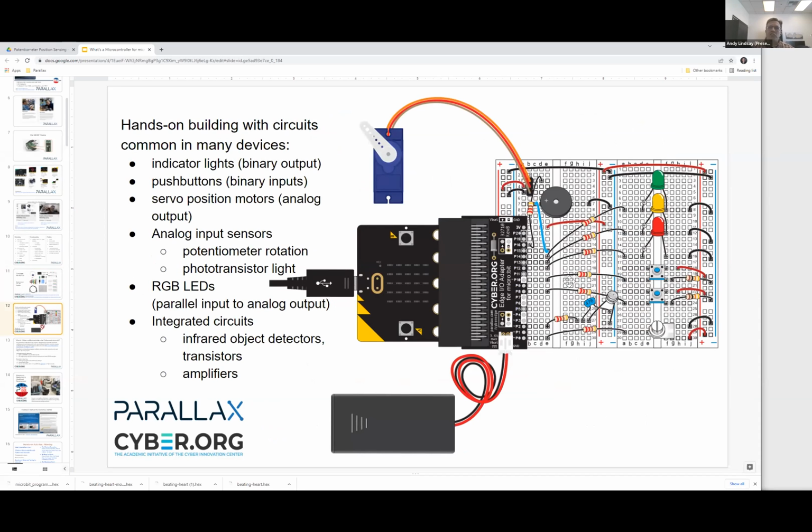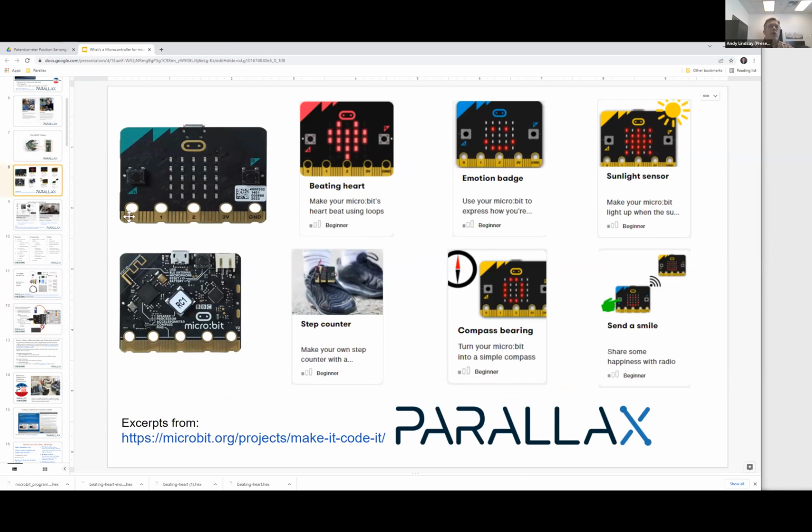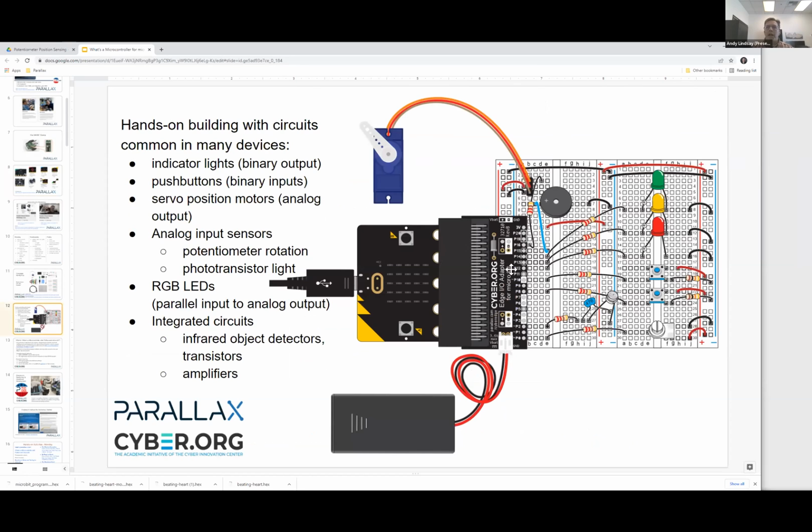Now, this is just a quick example of how you can actually do a pretty involved application circuit once you're not using just the microbit. Now, when you have the microbit alone, all you've got are 5 little pads that you typically use to connect alligator clips to. They're labeled 0, 1, 2, 3V, and GND here. And only 3 of those are really good for signals. The other 2 are just power connections. But by plugging it into an adapter that plugs in turn into a breadboard, now you can do all kinds of neat stuff.